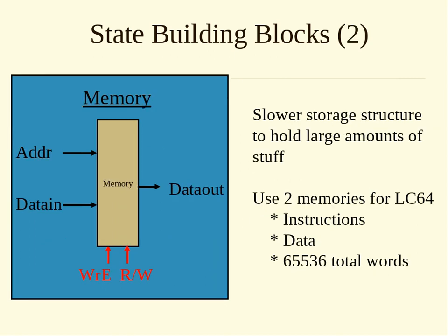Memory. Okay, going through, you have an address and a data in. So, in other words, if you are reading from memory, then it takes your address, goes into the address in memory, and outputs that value. If you're writing to memory, it takes the address and your data in and writes to that line, and data out is superfluous. How do you know what you're doing?